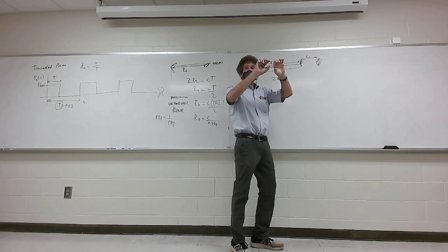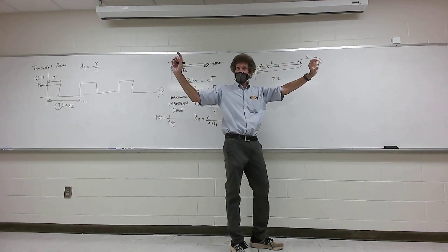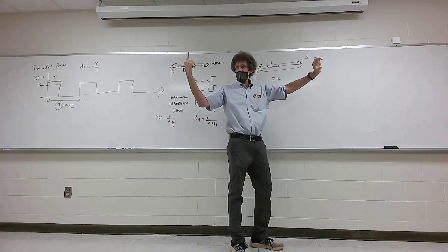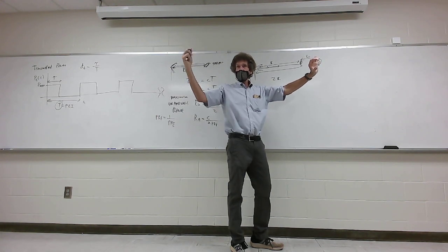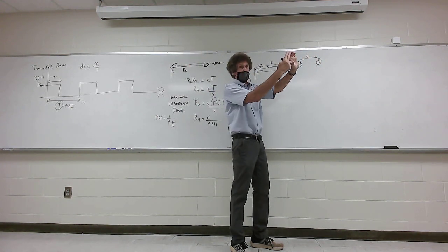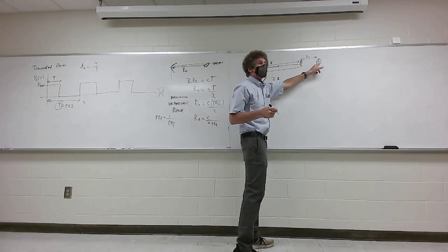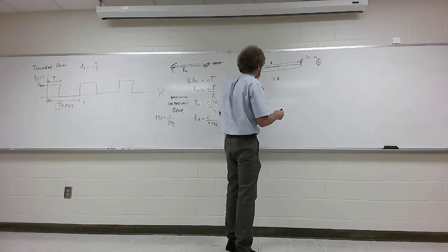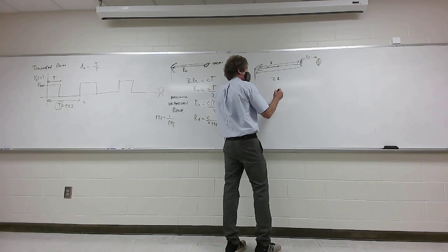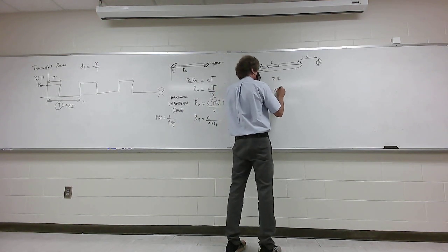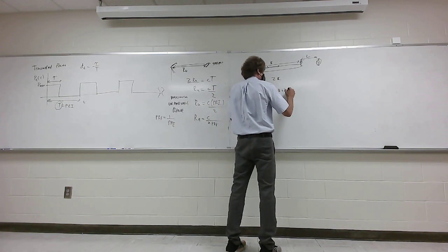So if you have a very long conducting object, and you send a pulse and hit that thing, you'll get a huge reflection off the very front, and you'll get a reflection off the very back. Even though your eyesight doesn't see the very back, the radar signal will. It'll reflect off. So there are 2 points of scattering right there. This is the shortest distance. The longest distance would be 2R plus 2L. Follow me?